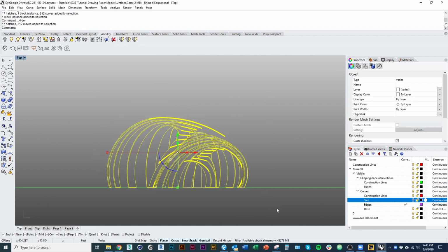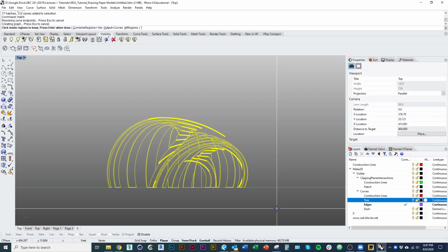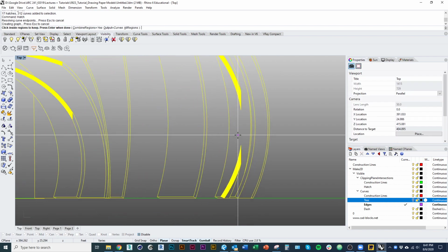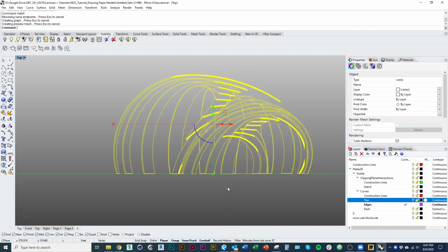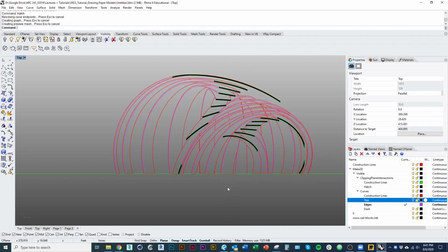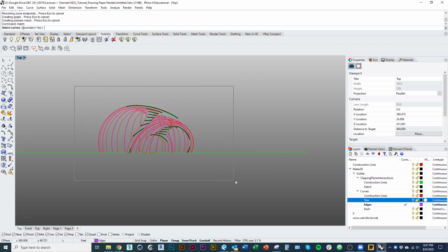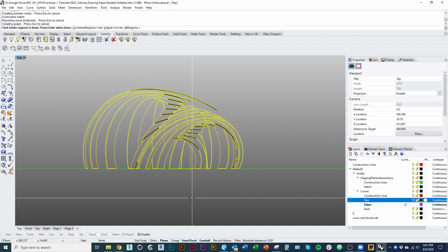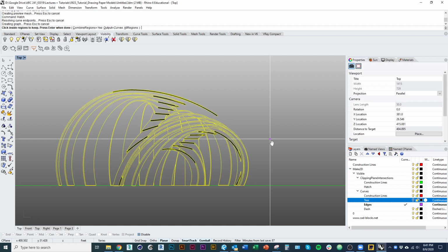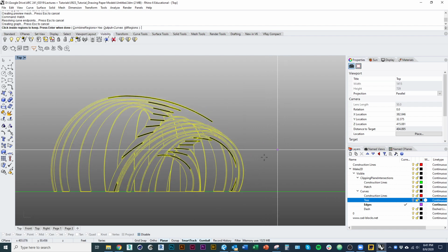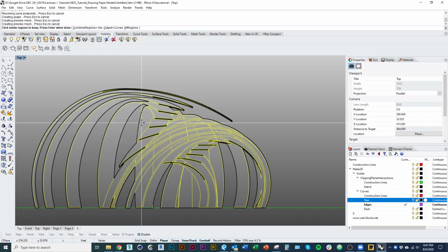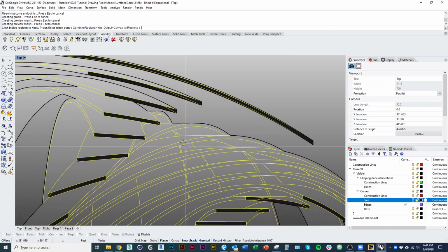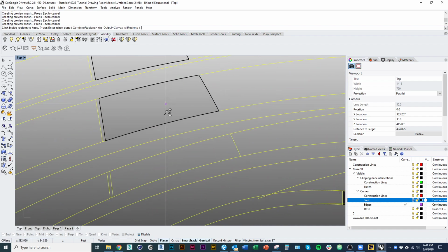And then going back to just my base drawing, what I could also do now is hatch it. And what I might do is just hatch the whole thing. So when you do hatch and you do boundary like what I just did, I'll type in hatch. See our option is set to boundary. It'll say select curve, so those are the curves I want to hatch. Press enter. And then if I just want it to hatch everything that it can possibly fill in that has a closed outline, I can just click out in space somewhere and it'll fill everything. And then I just have to go through and unfill areas where we would actually see through it.